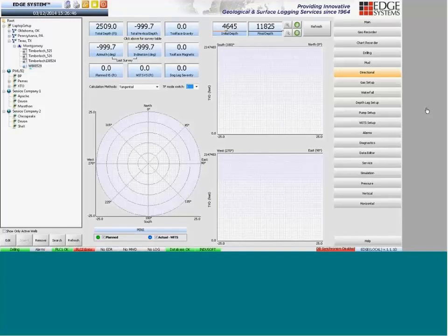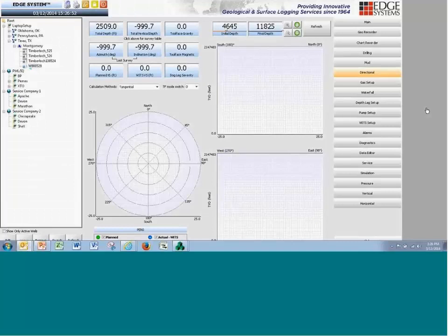So the first one is, I have a question. What kind of InduSoft objects are shown in this page? I believe you were on the mud logging page. That's a standard trend control from InduSoft Web Studio. As you know, the trend control is quite flexible in InduSoft Web Studio. You can change orientation to horizontal, vertical. You can also display data not only based on time, but also based on other numeric values. So in the mud log, the data is typically displayed based on the depth of the well.